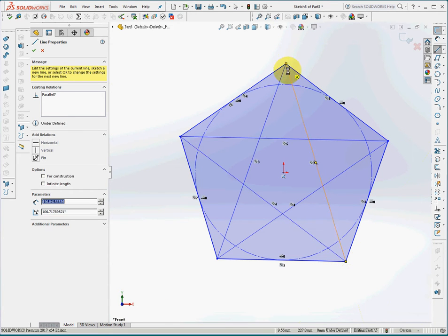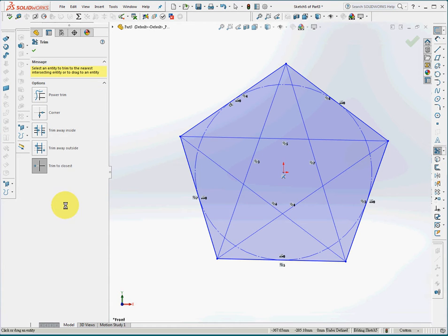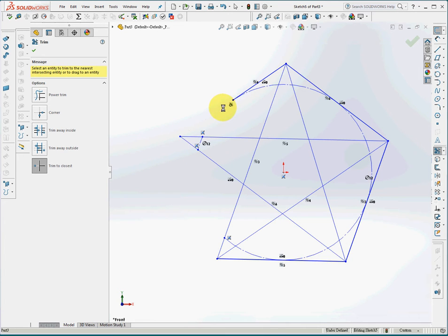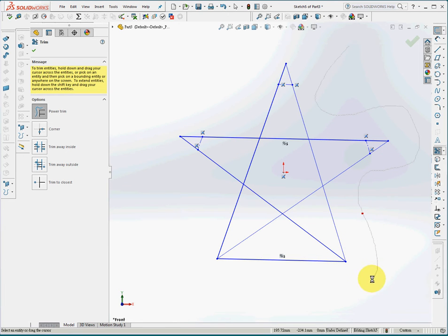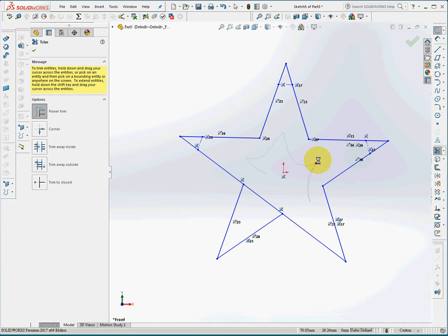And we'll talk about scissors. For the last option, you can cut whatever elements using your mouse click. For the first option, you can drag through the sketch, and whatever element you touch, you can cut.